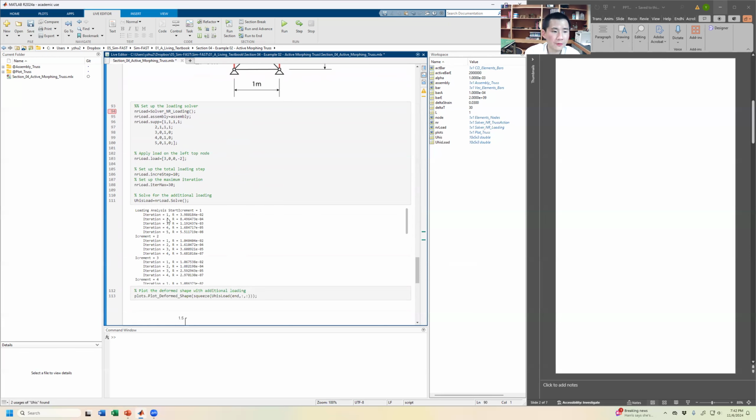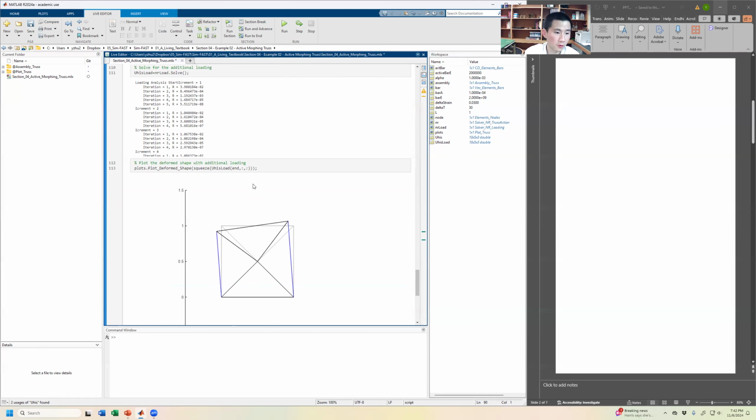If you only have 2 iterations and you find the equilibrium, perhaps what you can do is make your increments fewer. So maybe instead of using 10 increments, I can use 5, and I have a little bit more iterations there. If it's unable to find the equilibrium after, let's say, 30 iterations, then in that situation you want to make more increments in your solution.